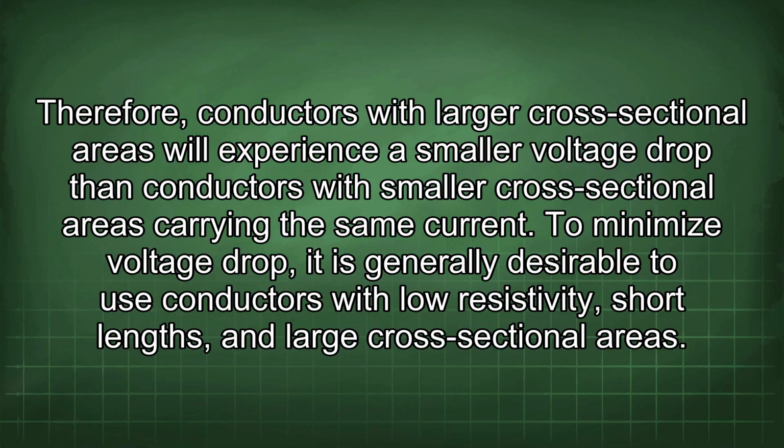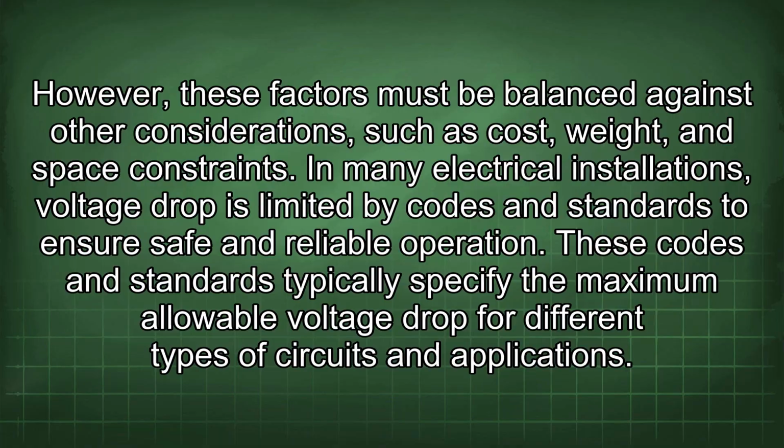To minimize voltage drop, it is generally desirable to use conductors with low resistivity, short lengths, and large cross-sectional areas. However, these factors must be balanced against other considerations such as cost, weight, and space constraints.